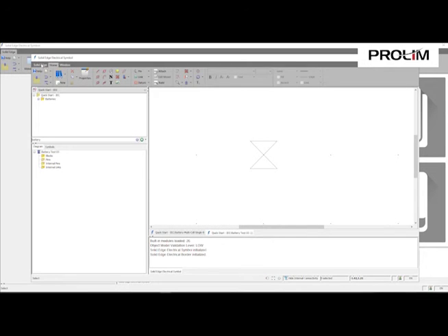We also have the ability here. If I go to the Solid Edge tab, go to Files, I can actually import DXFs. So, for instance, if customer X has been using AutoCAD to do all of their unintelligent schematics using blocks and lines, and spent a lot of time creating that stuff, now we have the ability to reuse those existing symbols from other platforms by importing the DXF right into the symbols user interface.